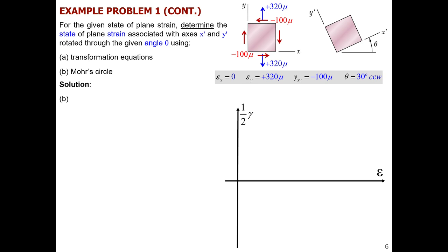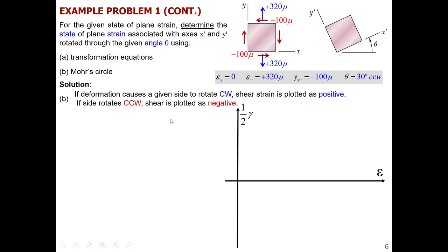Now we have a different agreement for the signs of the coordinates that we use in a Mohr circle. Some of them will become negative or positive depending on whether they rotate clockwise or counterclockwise. I can already see that this pair needs to be in different directions of rotation to keep this element in equilibrium. We cannot put them in the same direction, otherwise they will start rotating this element. So they are the same sign, minus, but when we put the coordinates here, one of them will become minus and the other will become plus. We need to identify all those that rotate clockwise, so they will be positive, basically this one and this one. And those that try to rotate the element counterclockwise, this one and this one, will be negative.